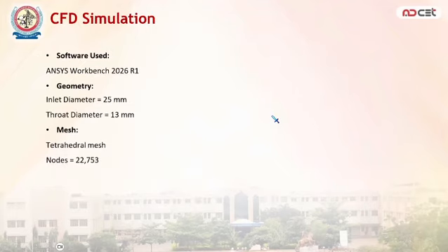The next slide is about the CFD simulation setup. To validate these physical findings, we performed a numerical analysis using ANSYS Workbench. We modeled the exact geometry of the experimental setup, featuring a 25 mm inlet that converges to a 13 mm throat. To ensure accurate computational results, we generated a tetrahedral mesh containing over 22,700 nodes.